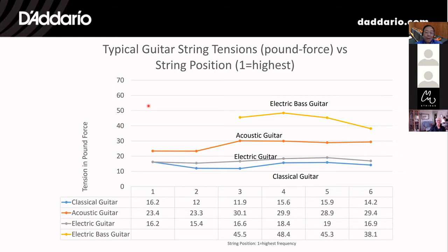by modern steel cores, typically brass alloys wound on steel cores. So with the higher tensions and the larger diameters and the use of metals, which are not as flexible as synthetics, it turns out that the third string of an acoustic guitar needs to be wound. Otherwise, the bending stiffness is too large if you use a plain steel string for that.